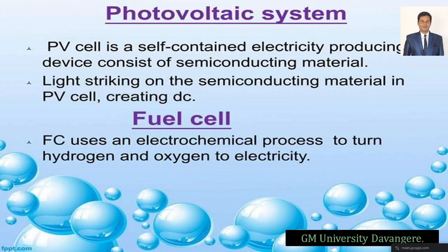Photocells will try to produce energy from the photovoltaic modules, converting light energy into electrical energy, right? Through the emission of electrons, they produce a voltage across the cells. So when light hits the semiconducting materials, the PV cells, which may be amorphous or silicon cells, right, they generate voltage. It will create DC voltage. Then you can give it to the inverters, which will convert it back to AC, right?